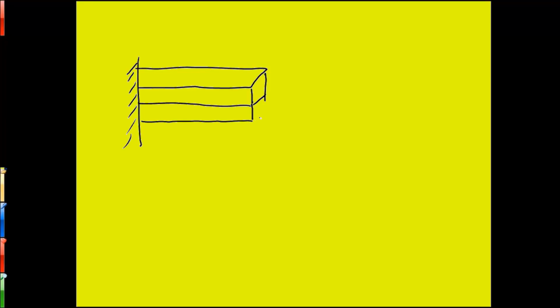Now let's say that we have a rod of length L, just like we did before, but now we're going to say that this rod is twice as thick as the one before. So we're going to double the area of the previous rod. When we do that, what do we expect is going to happen? Well, we apply our load of F on the end of it, and because each one of these halves is resisting against the force that we apply, it's as if this one is receiving 1/2 F, and this half of the rod is receiving 1/2 F. If this is the case, then we expect each one of these bars is going to extend by 1/2 delta L, so half the delta L that the one bar before extended when we applied the force to it.